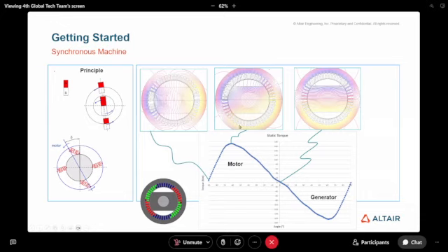In a permanent magnet machine, we usually have the maximum torque if there is no reluctance variation. For a surface permanent magnet machine, the maximum torque is obtained at 90 degrees. Here, since we don't have magnets and we have only the reluctance, which we play on, the maximum is not at 90 degrees, but somewhere between minus 70 and minus 60.